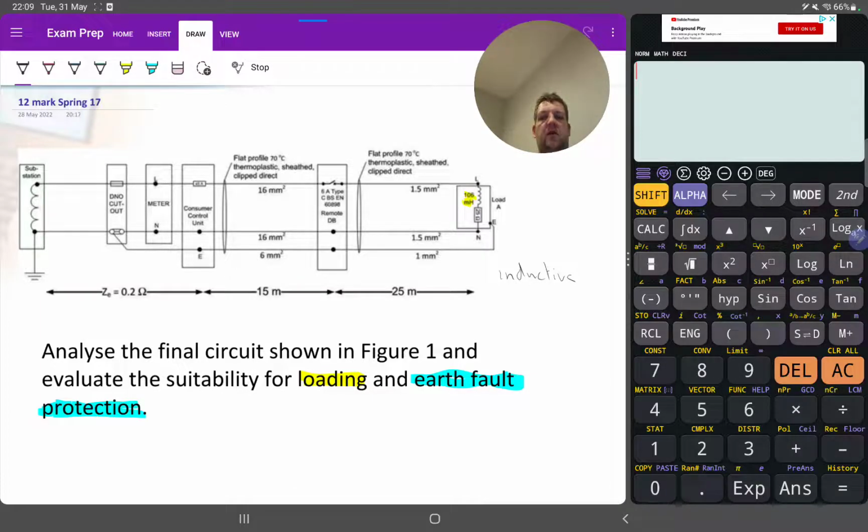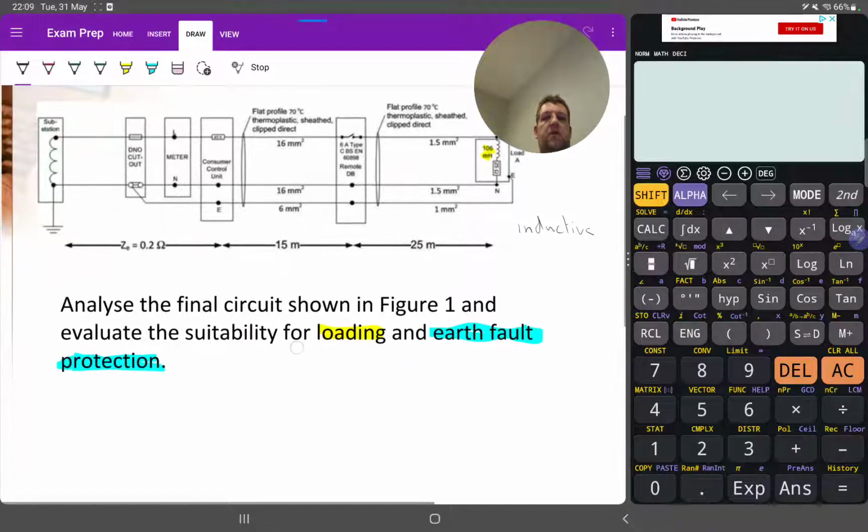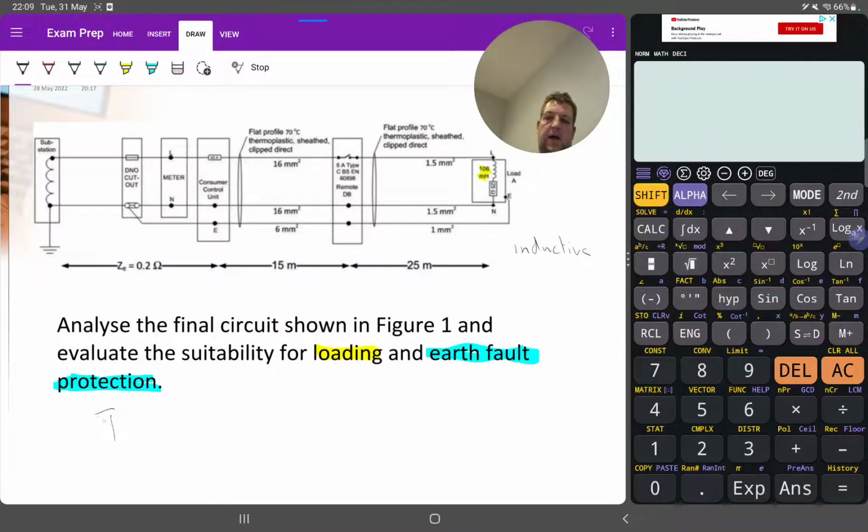So what we're aiming for is to get the load in. So we're looking at getting a current. To get current, we're looking at a few things. So current is your I equals V over Z, because in AC it will be voltage over Z, rather than resistance as in DC. We don't have an impedance value, so we need to work impedance out. So to get impedance, we're looking at Z equals the square root of R squared plus XL squared.